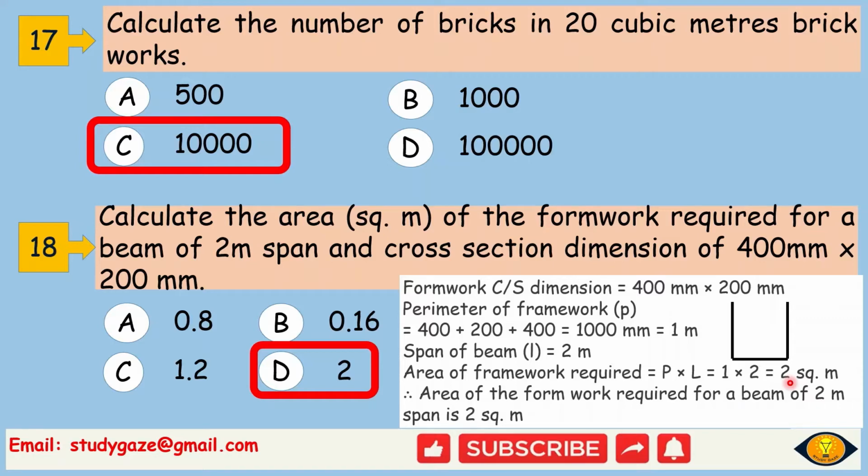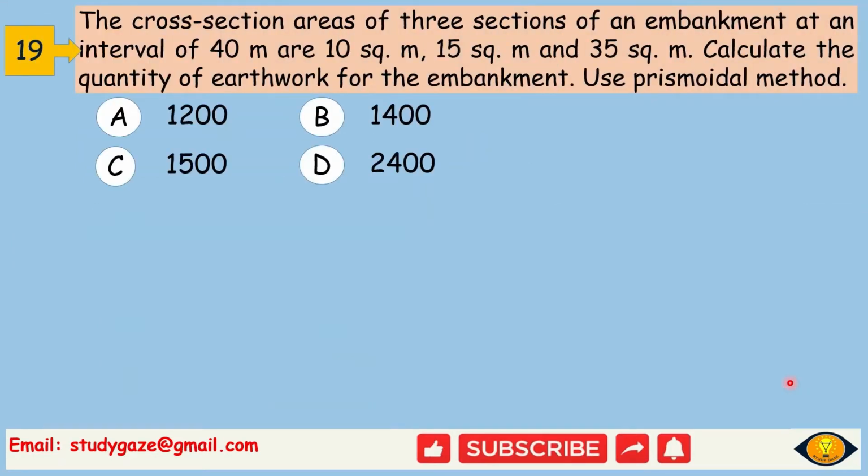Next, the cross-section areas of 3 sections of an embankment at an interval of 40 meter are 10 square meter, 15 square meter and 35 square meter. Calculate the quantity of earthwork for the embankment. Use prismoidal form method.